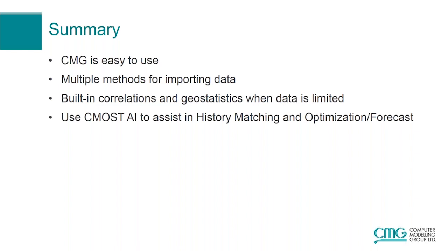You can also use the hydraulic fracture type of gridding, where you can use compaction dilation tables where the conductivity of the fault is a function of pressure change as well. So there are several ways that you can model it, and you can definitely use the LS-LRDK grid that we use for hydraulic fracture to capture the conductivity variation with pressure.